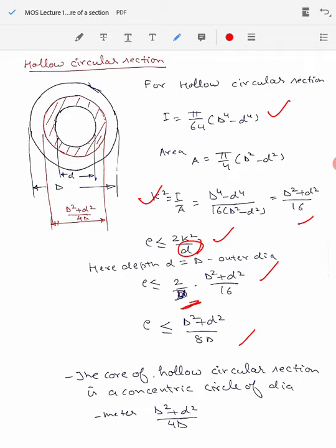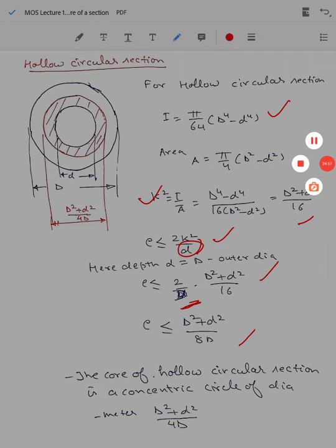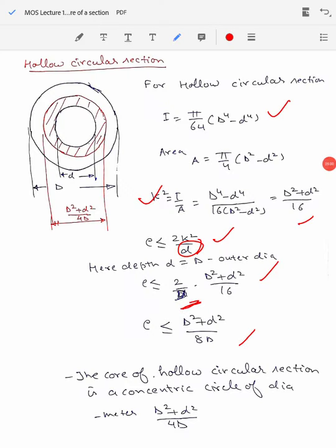So a treatment was carried out. There was some drilling carried out at the outer periphery, and then the diameter of these columns was increased, and now you can see that there are certain circular columns which are much larger in diameter in comparison to the other columns. This maintenance work was carried out, and by that we were able to suppress the production of tensile stresses or cracks in these columns. You can see some other examples also. I would suggest you look around yourself and see where you can find such eccentric loading in machine components.